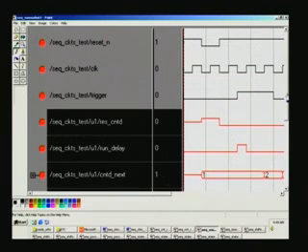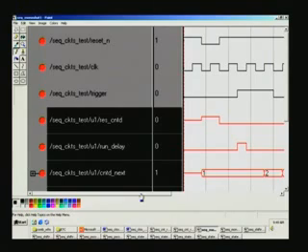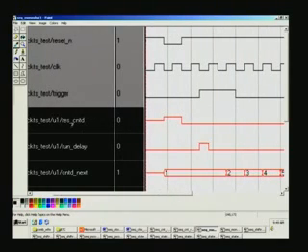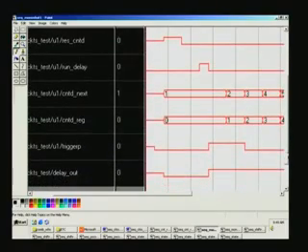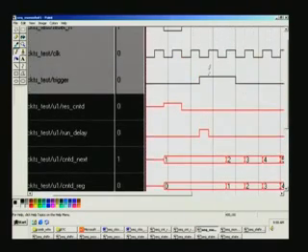So if you see here, this is the trigger, and this is resetting the counter, and this run delay is the one which senses the rising edge of the trigger. So the trigger is going high right at this point, and the earlier value of the trigger is 0, but that 0 must be preserved in trigger P as such. You see here, trigger P is actually 0 right at this point, whereas it becomes 1 at the rising edge of the next clock pulse, right at this. So that makes it clear, right?